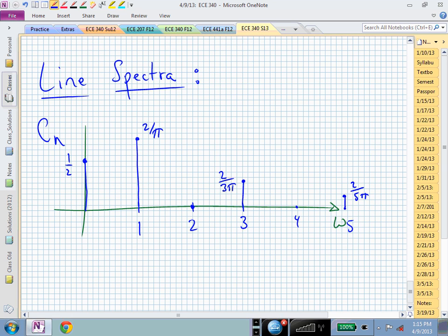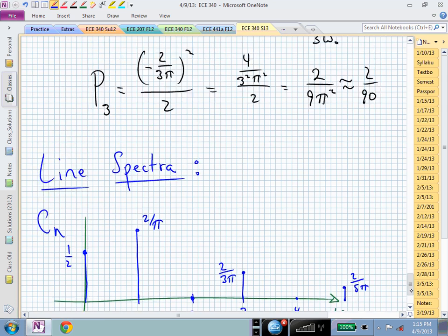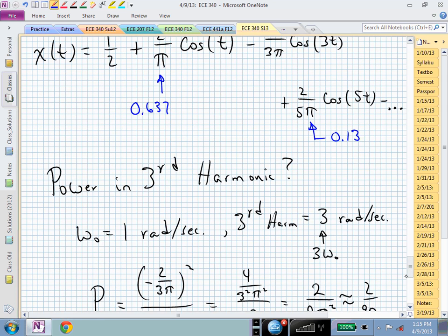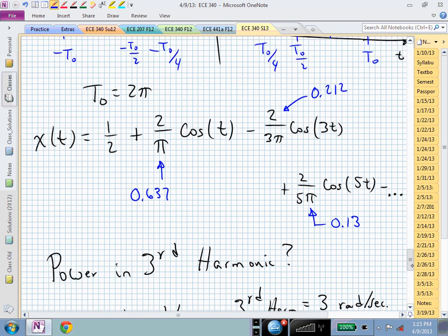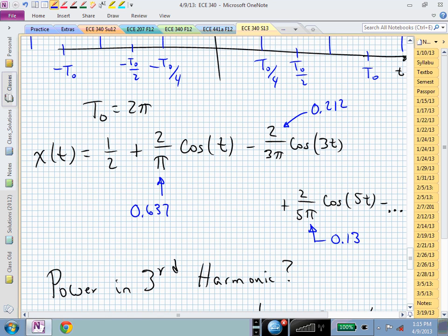Yes? So the reason I'm doing the absolute value is just so that I can show you that you can also represent the phase. There's 2 pieces to the line spectra. There's a magnitude piece and there's a phase or angle piece. And what I'm doing is I am explicitly saying I want to just create two plots, a magnitude plot and an angle plot.